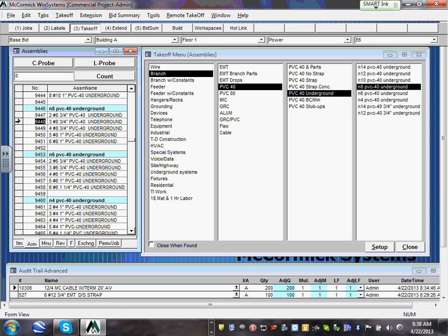If it's 2 circuits, why 3 conductors? We're going to have phase 1, hot 1, hot 2, and a neutral. And you also need a ground with it, because it doesn't come with a ground. Make sure you account for this one; you're going to count the ground. So you're going to have 4 conductors: phase 1, phase 2, the neutral between both of them, and a ground. Cool? And click on it like I said here.